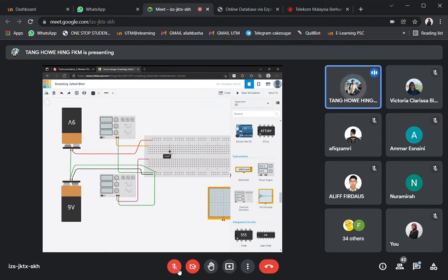Okay, and now this one for the op amp. Okay, so this is pin number 1, 2, 3, 4, 5, 6, 7, 8. So pin number 4 has to go to negative power supply, which is here. And then 1, 2, 3, 4, 5, 6, 7.